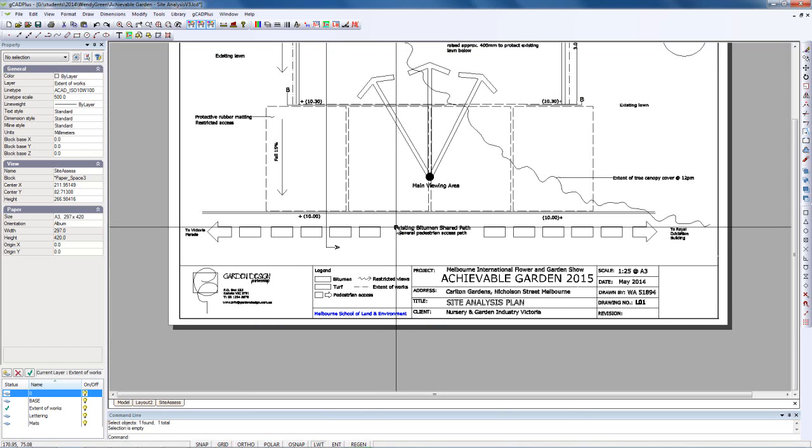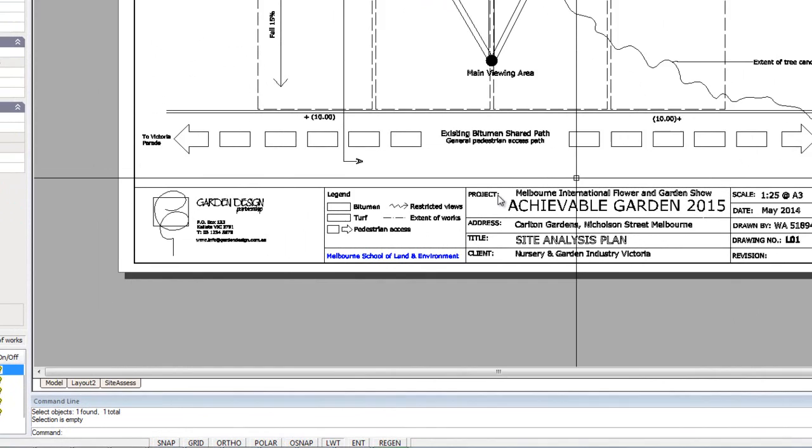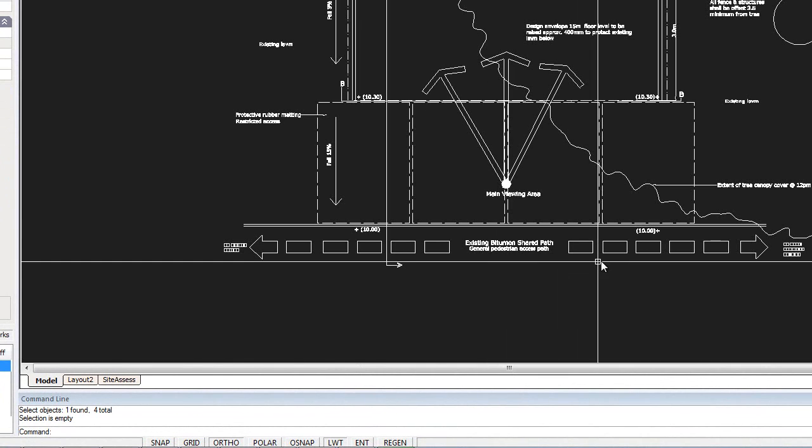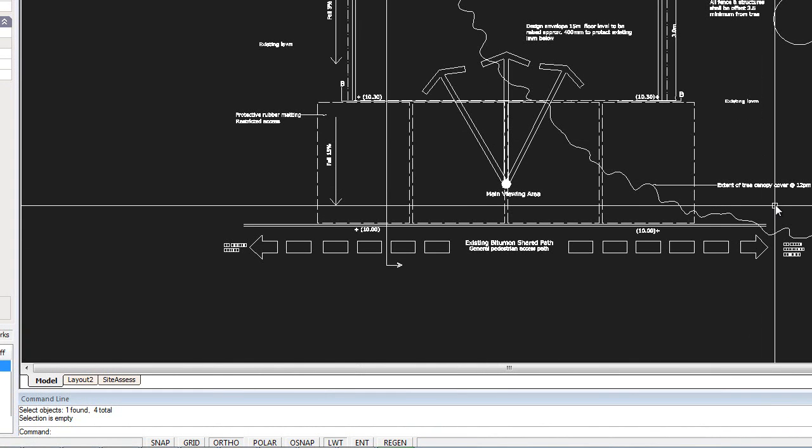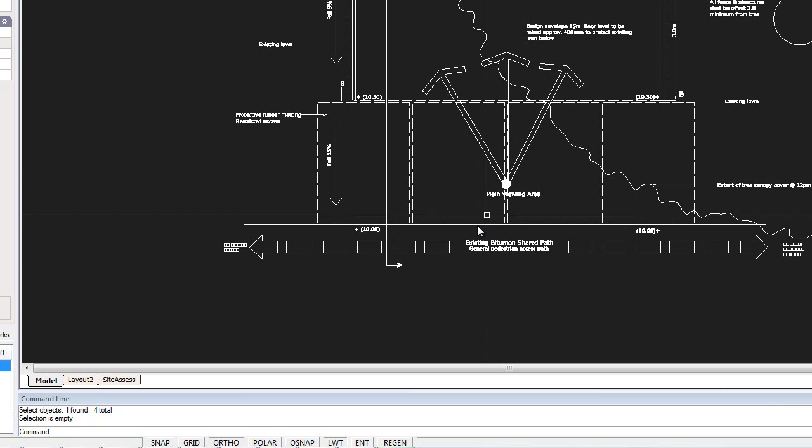It's really important to separate out the true model from the other presentation issues, which are project name and scales and so on. I've removed the scale bar and the north indicator because I would prefer those to be in model space. So I would put a north indicator in here and a little scale bar down in that area.